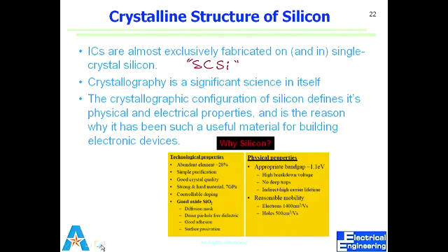And do we get control over conductivity or not? So high breakdown voltage, so it takes a certain voltage before we can bring it to conduct. No deep traps, indirect, high carrier lifetime. We'll look at carrier lifetime later on. And mobility for both is reasonable. We'll look at mobility also, and which value is important. But essentially, silicon was used for the oxide, and everything has been good about it.